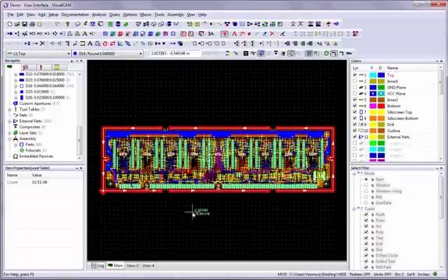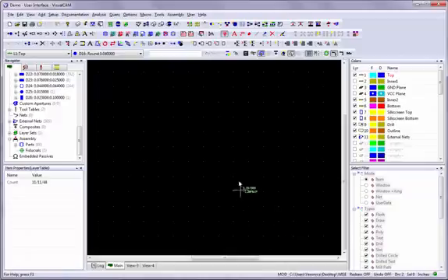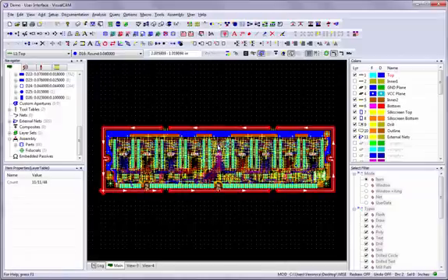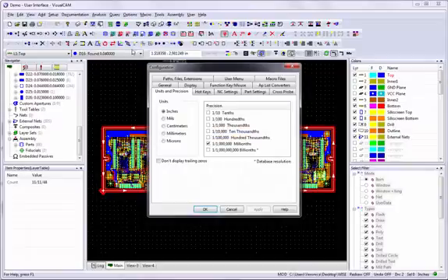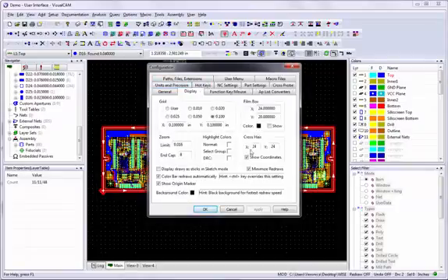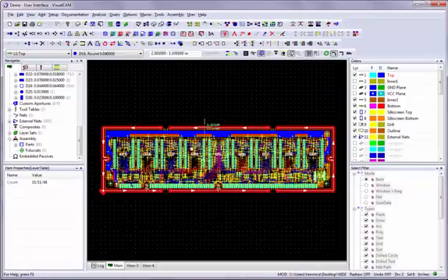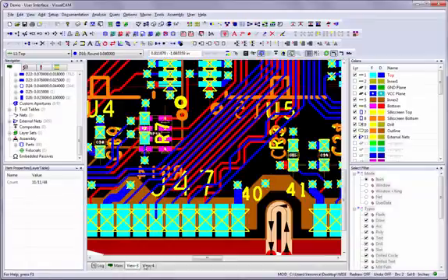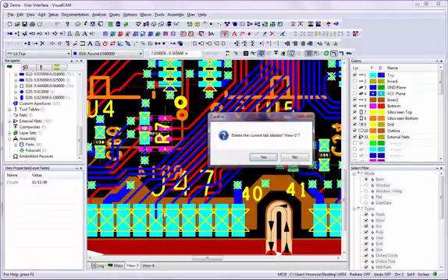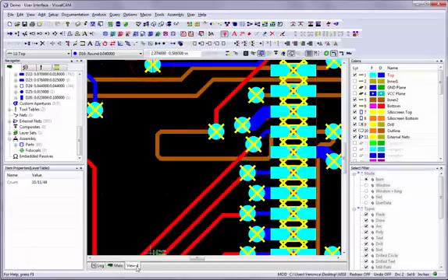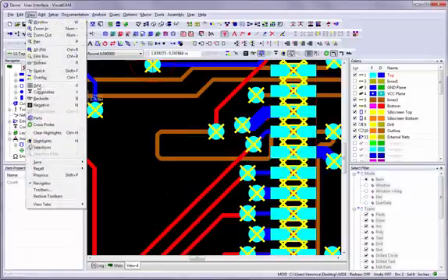And last but not least, the cursor, or crosshair, is used to select objects, commands, buttons, etc. in the workspace. You can control the size and whether or not to show the coordinates along with the crosshair in the Options Configure Display dialog box. Note that all changes made to the toolbars and dialog box placements are automatically saved in the registry when you close VisualCAM, so when you open it again, the screen will appear exactly as you left it.